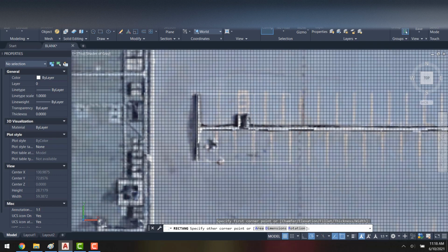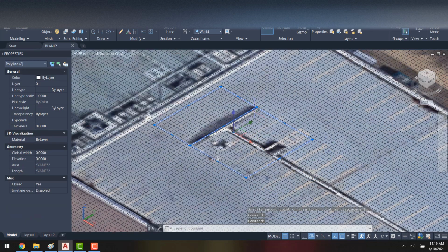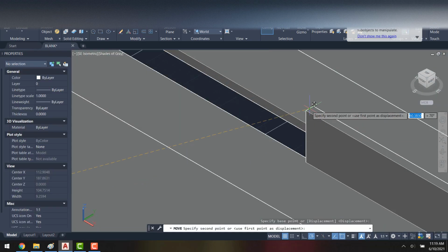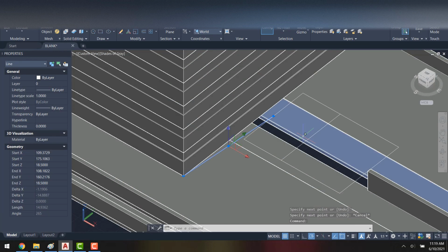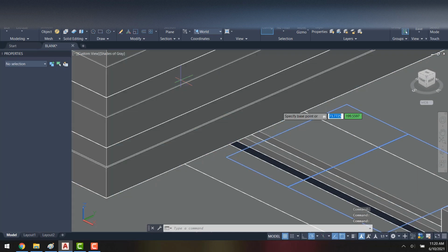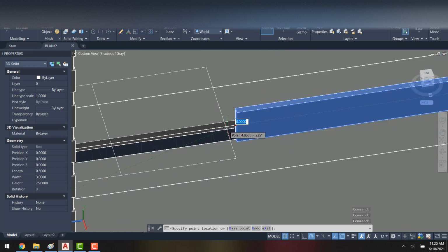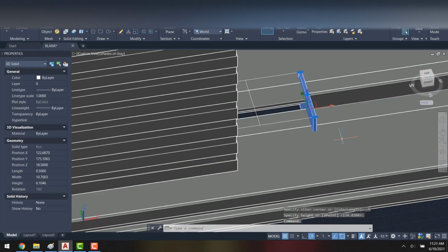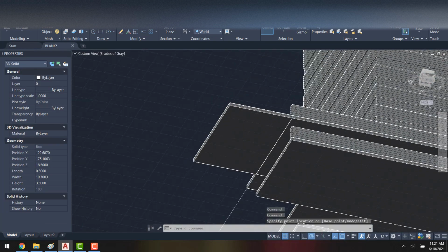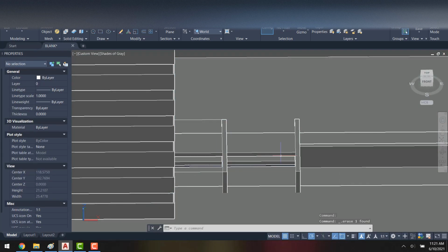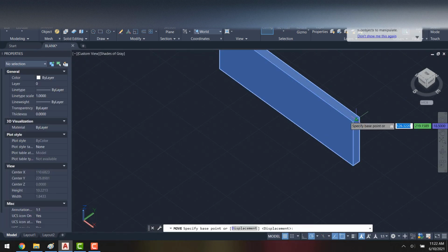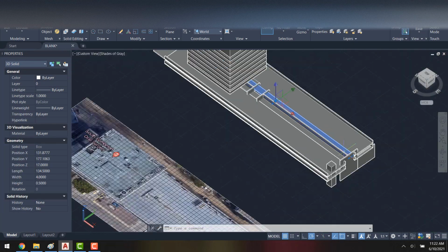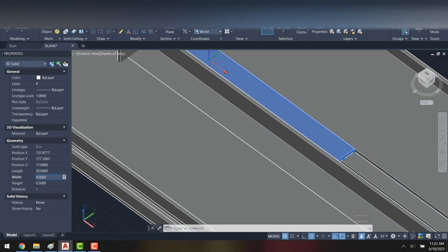So with that, as long as you're going off of the dimensions from one of them as your master, and always say, okay, this is going to be it, and then just eyeball it between the 3 different websites, that's fine. But don't measure the width of the building on Google Maps and then the length of the building on Google Earth, because you're going to end up with it being out of scale.